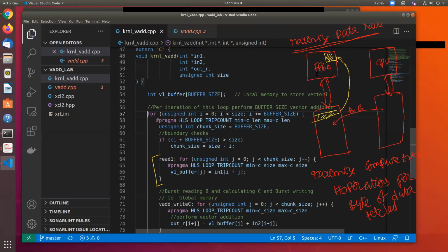The FPGA that you use, for any accelerator, actually has what we call a shell, which is created. It consists of IP to do communication from the host and also to read from DDR. And then there is a runtime library, which is a layer below OpenCL. So every piece of hardware that supports OpenCL has to implement those runtime functions.